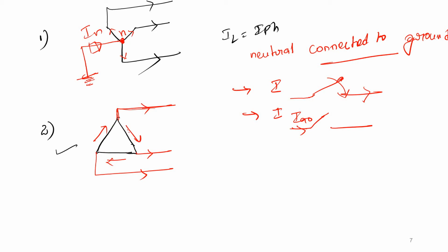Yes, because of the zero sequence component of the voltages, there will be some zero sequence currents. That means if there is a delta connection, within the circuit the zero sequence currents will be flowing, but to the main lines there won't be any zero sequence currents. What does that mean? In the delta connection, for the currents to flow within the circuit, we should put some switches at the shunt side.